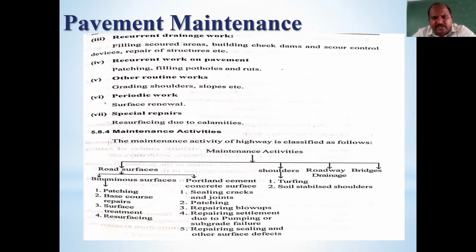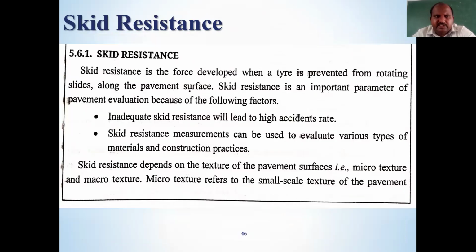In Portland cement concrete surfaces, we are seeing sealing of cracks and joints, patching, repairing blow-ups, repairing settlement due to pumping or subgrade failure. Finally, repairing scaling and other surfaces. And also in shoulders, turfing and stabilized shoulders. In the roadways and the bridges, we are using drainage.